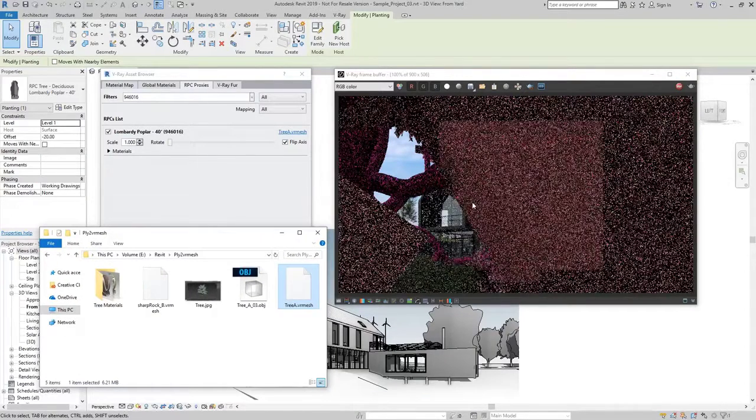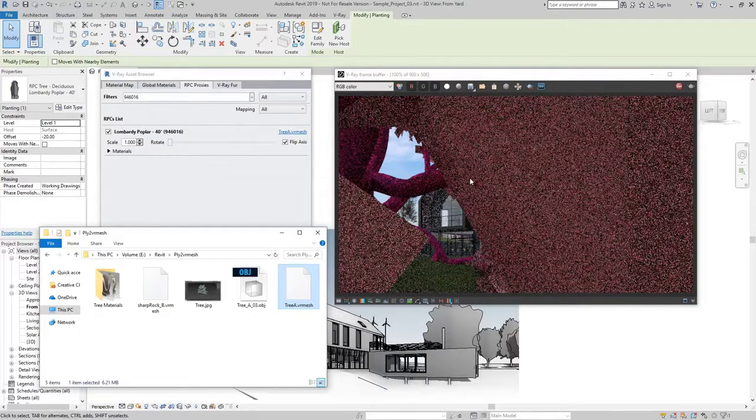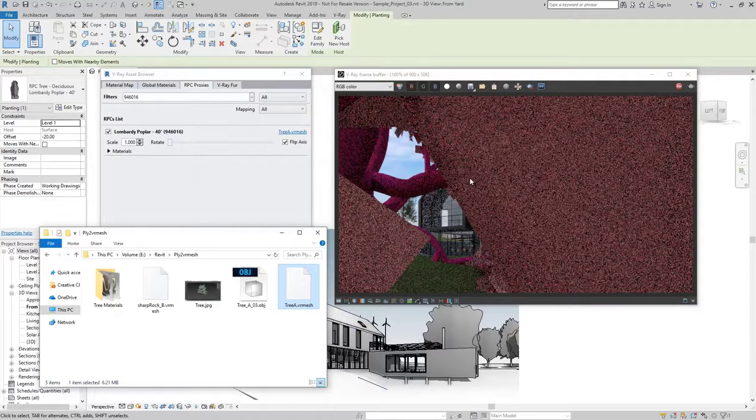What you see at that moment is totally normal because proxies are exported from different 3D platforms with different units and coordinate systems. So do not be surprised if when importing the proxy, it looks overscaled or its vertical axis is flipped.